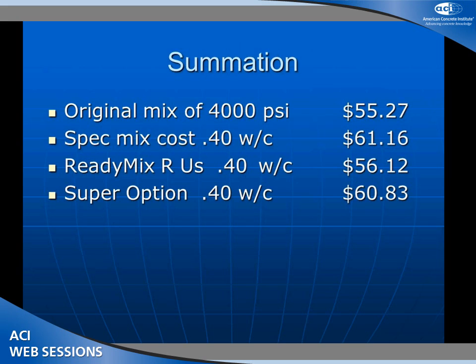The last part of the story is that the engineer agreed to take a risk with me and let me design the mix, and on the next two pours on grade, still in the middle of summertime, we cut the cement, put Super P in, and the problems went away. He got a better finish, and he got his FL numbers all to meet. So that's been one of the interesting challenges, guys and ladies, and sometimes we'll see that 0.35 water-cement ratio pop out there for air-entrained concrete. And that's a real fun one, because remember, we still have to finish and place and pump all this concrete.